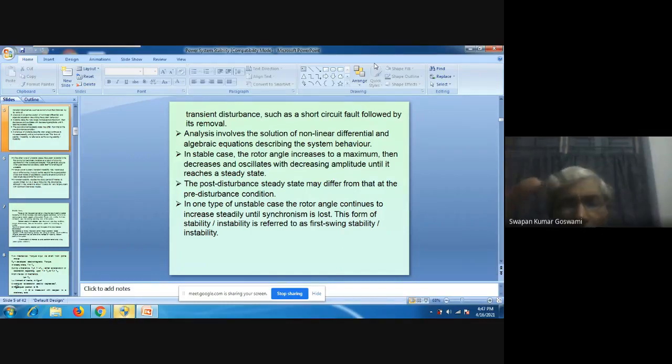When the faulty line is disconnected, the fault has been removed, but power will now flow through other lines. As the power tries to flow through other lines, those lines may become overloaded. Those lines may again be isolated by the circuit breakers because the corresponding relays may identify this situation as an overloading condition or even as a fault. So other lines also will be overloaded and disconnected.